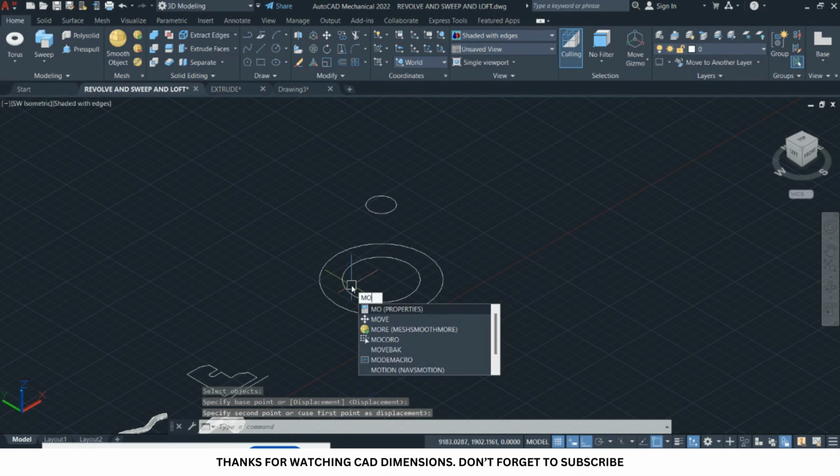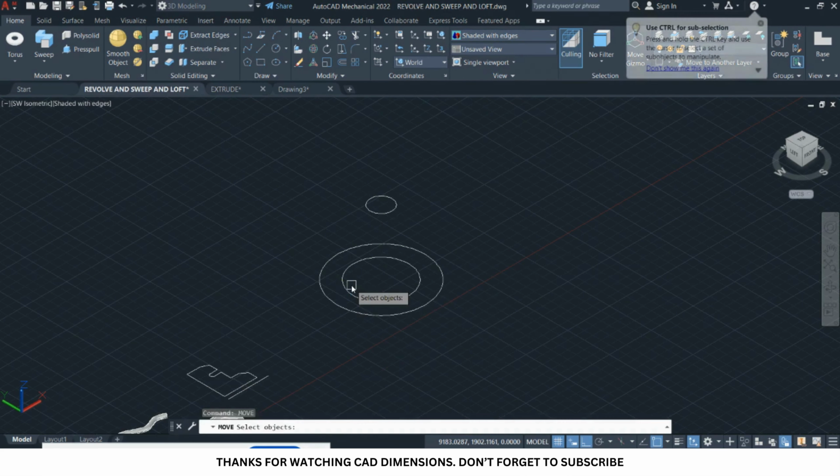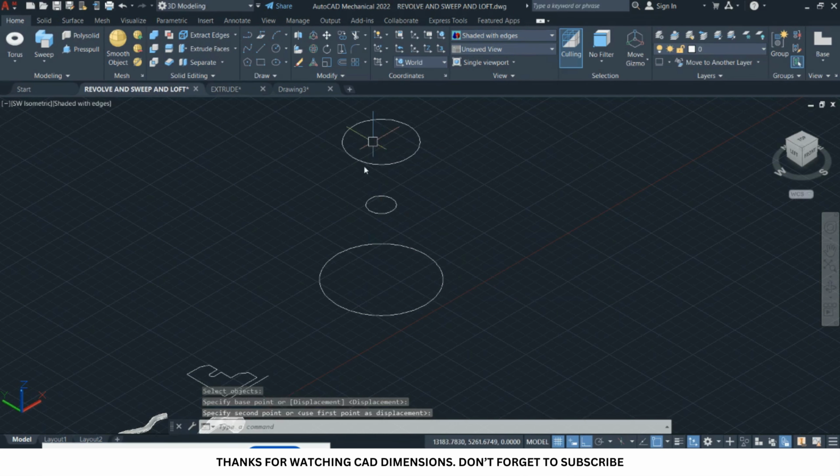Then I'm going to move the next circle, that is this, press enter, use this as the base point, then move it to this. This basically makes it very good for you to create a loft.